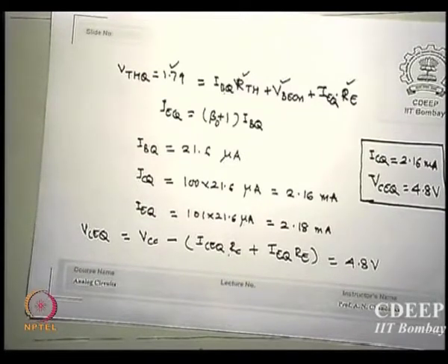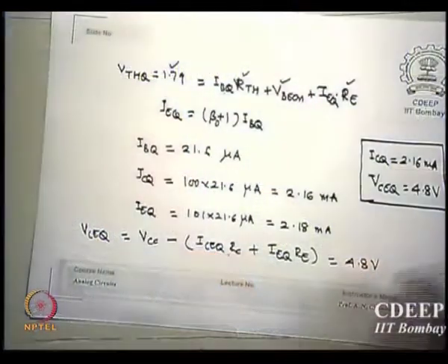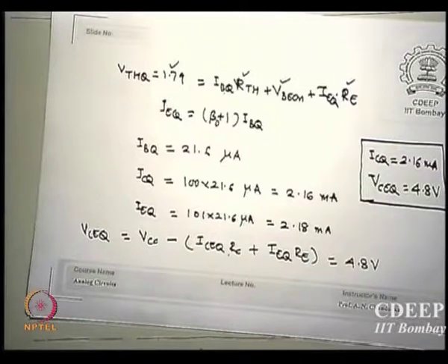The choice of RC, RE, RB1, RB2 should be such that you come close to 50% of the VCC. Please remember this is not exact 50%, it is less than 50%. It can become 5.2 also or 5.4 also or 4 also. Even 3.5 is good enough, because VCE will be in linear region as long as it is not less than 0.6 volts.